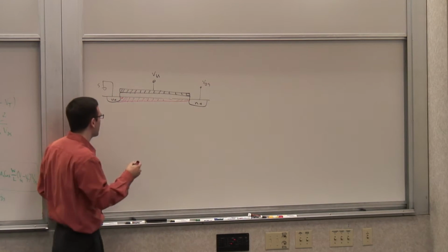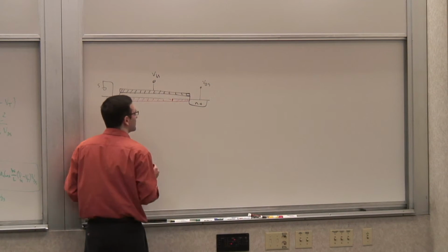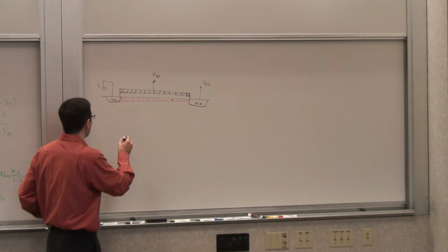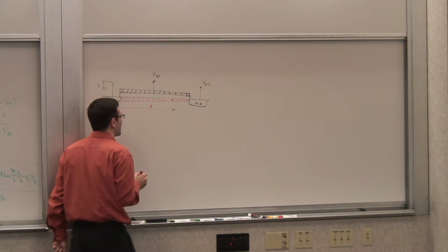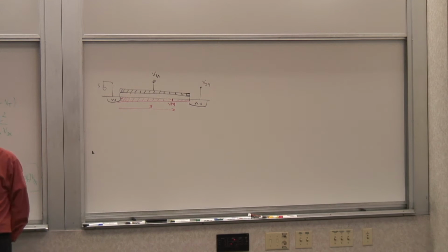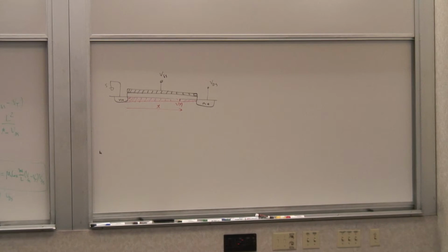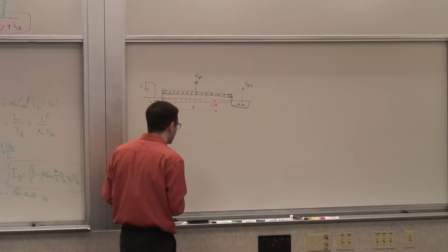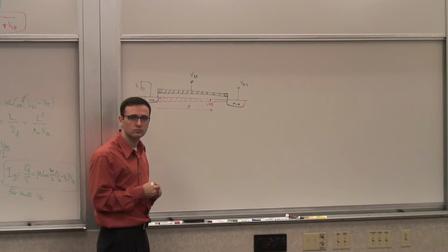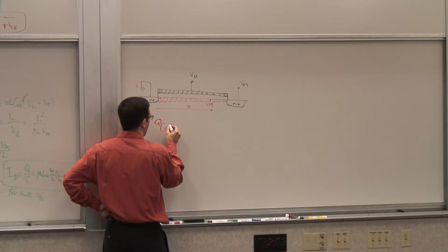What is the density of free electrons at some point? So let's say surface inversion layer charge at some point here. How do I calculate that? Well, let's say that's this point x on this axis. So let's call this V of x. If I know the channel voltage at that point, can you tell me what is the surface charge density for that point? What is Q per unit area at x?